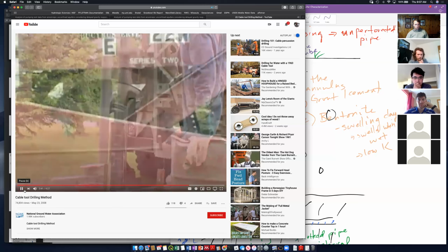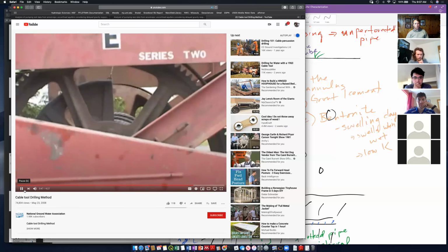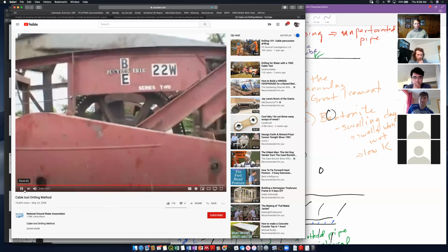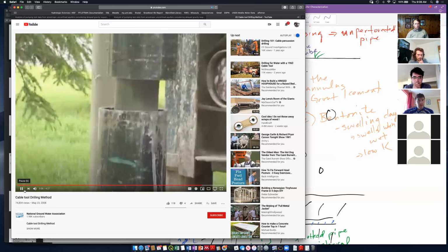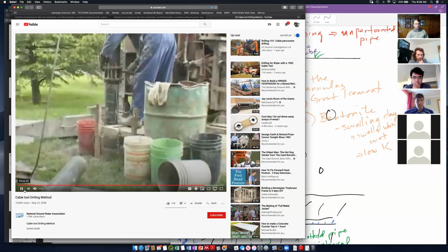The large bull wheel shown here supports the cable, which in turn supports the drill string. The speed at which it is turning here is typical of hole advancement in unconsolidated material. Ideally, casing is added in 10-foot sections to improve efficiency. Additional casing sections are usually welded, ensuring a watertight seal, as required per Regulation 903.